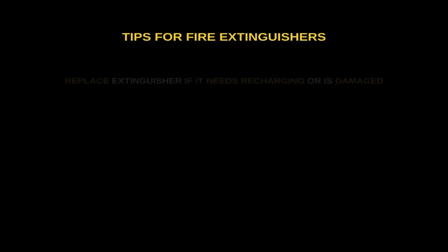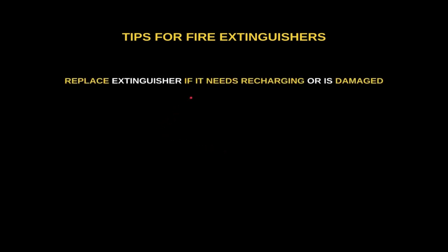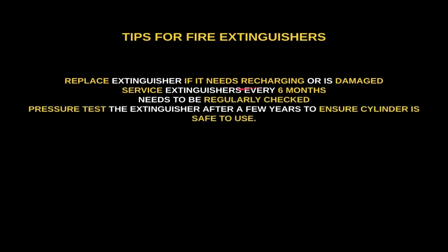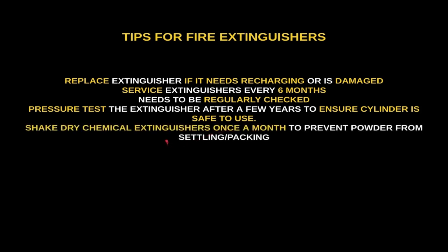Now, tips for fire extinguishers: replace the fire extinguisher if it needs recharging or is damaged. Service extinguishers every 6 months. This needs to be regularly checked. Pressure test the extinguisher after a few years to ensure the cylinder is safe to use. Shake dry chemical extinguishers once a month to prevent powder from settling or packing.